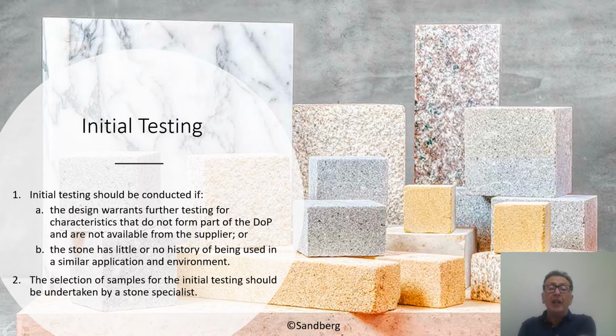Wherever possible, it would always be advised that the selection of samples for the initial testing should be carried out by a stone specialist, and that you don't just rely on materials supplied by the quarry itself. This ensures greater confidence that the material that's tested is reflective of the material that's going to be delivered for the project itself.